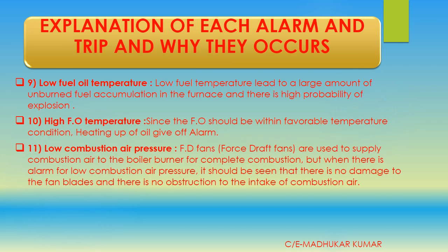Okay, now we are going to see about the low fuel oil temperature. Low fuel oil temperature leads to a large amount of unburned fuel accumulation in the furnace, and this carries a high probability of explosion. When you have low fuel oil temperature, of course it is more viscous and the atomization will not be proper. It will start dribbling into the furnace and this will cause unburned fuel to accumulate in the furnace. This can lead to backfire and explosion.